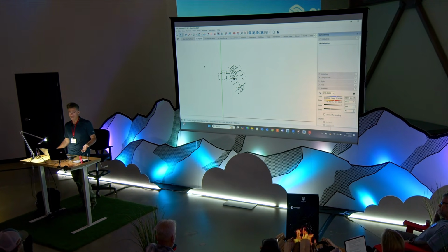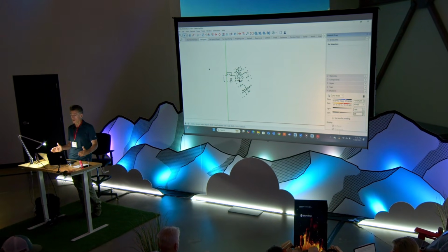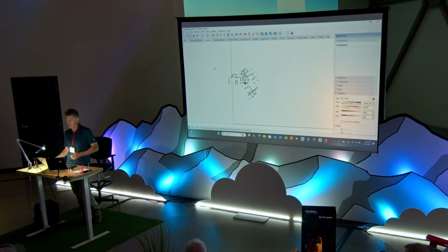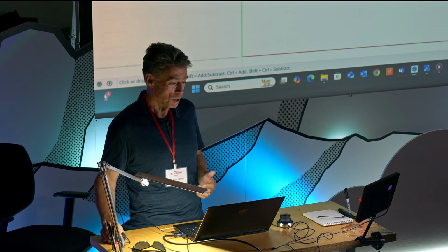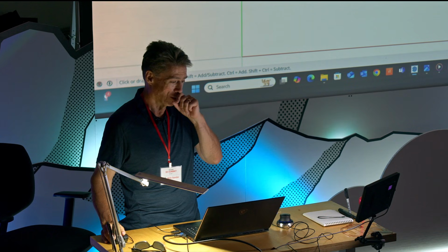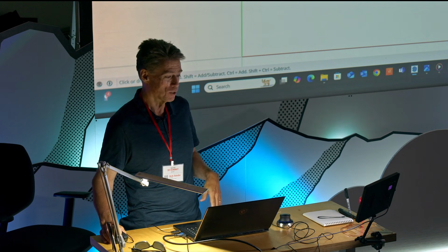A lot of times that's closets. In the case of the sauna, I had to look at what the sauna was and then add the drywall thickness and separate the studs enough to accommodate for that. But it's simple to do once you know. I've been doing it that way for years, so I don't ever think, oh, I want a 2-foot closet. I'm always like 2'1". All my door openings are shown as the frame.